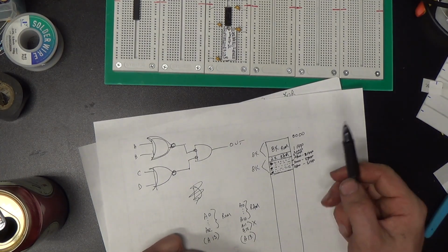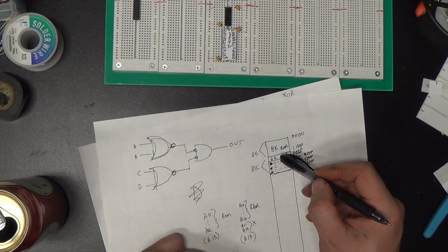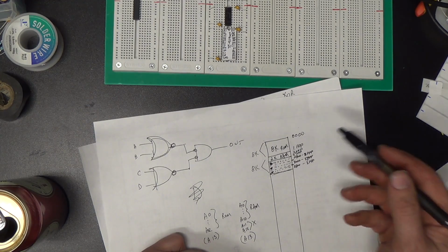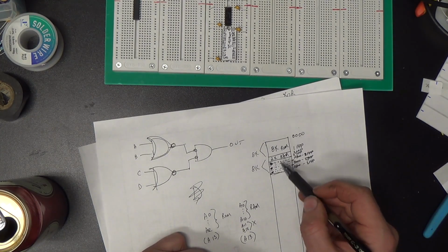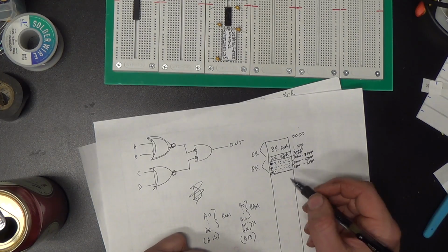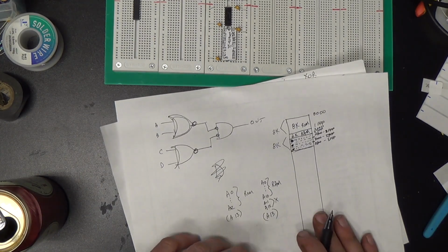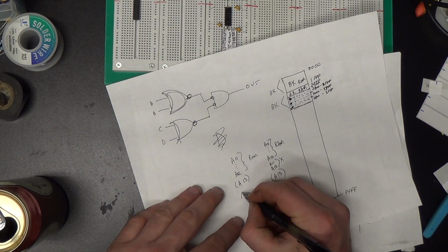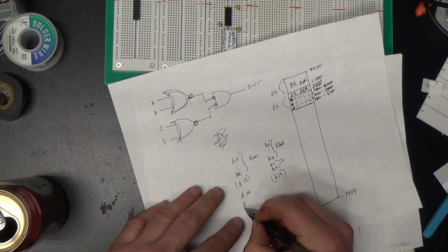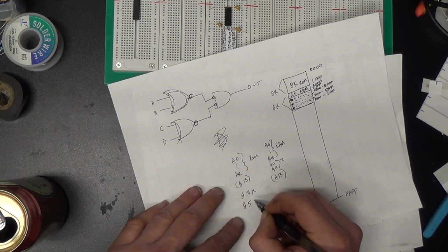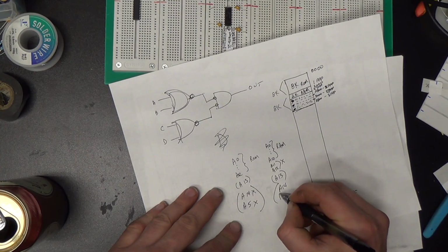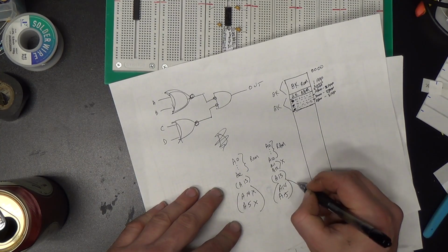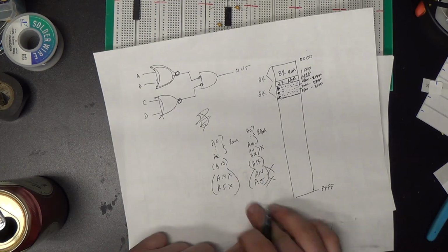As long as we inform our compiler or assembler where these segments occur in the memory map, it'll know not to generate code that touches these mirrored memory areas. And since we're also completely ignoring A14 and A15, we don't care what they are in either case.